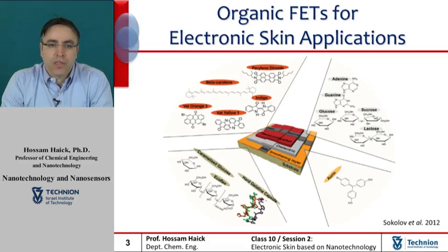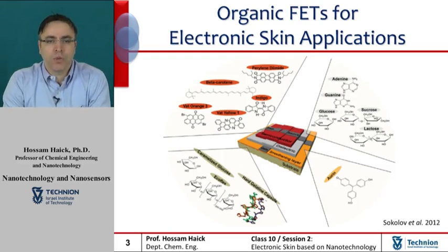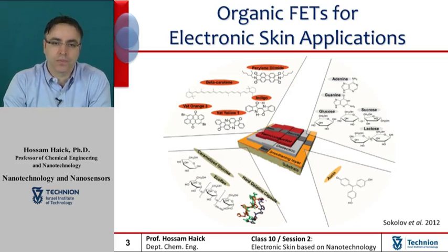Transistors that are based on these materials are fabricated on a degradable substrate, which is often coated with a smoothing layer to reduce the surface roughness of the material. Metal contacts form the gate, source, and drain electrodes, while dielectrics are needed as gate insulator and semiconductors are needed for gate-controlled charge transport between the source and drain electrodes.